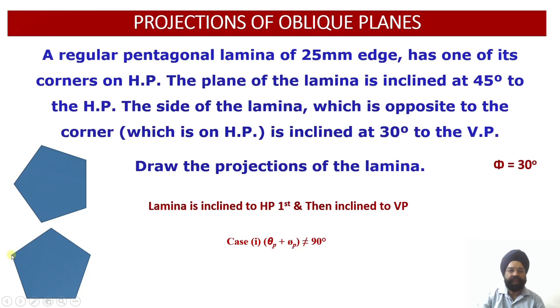This will be resting on the corner. Over here also, if I lift it this way, this will also be resting on the corner. But all these edges will get reduced, so the apparent views will be available on the horizontal plane in the top view. There will be no edge giving you the true length of the edge opposite to this corner.